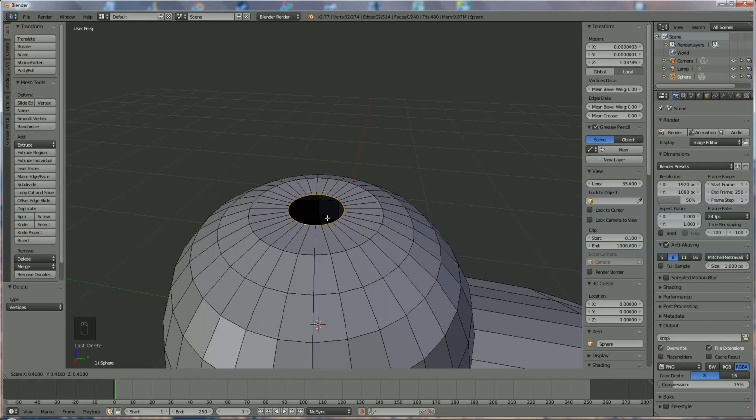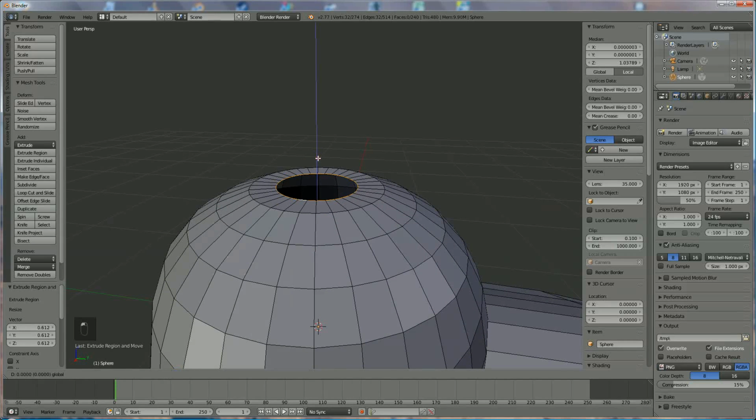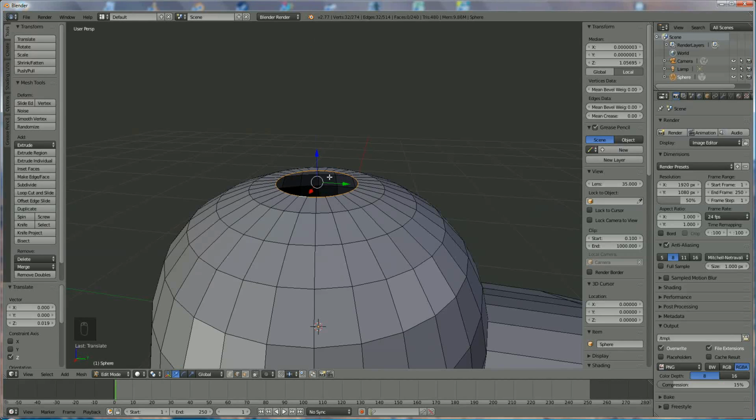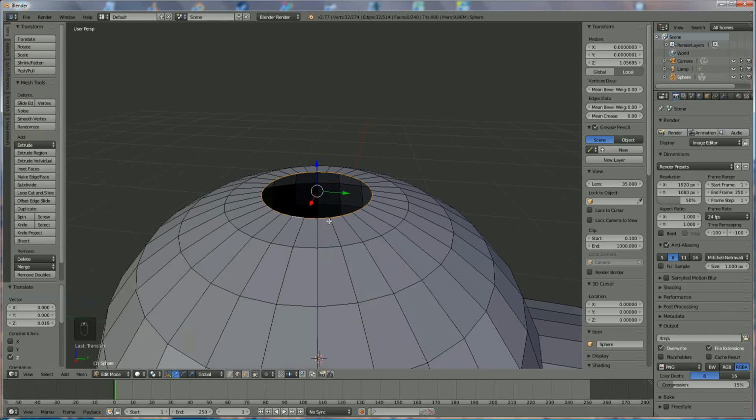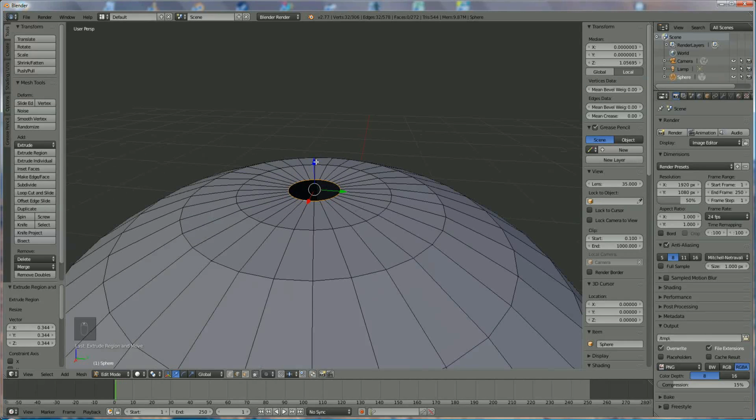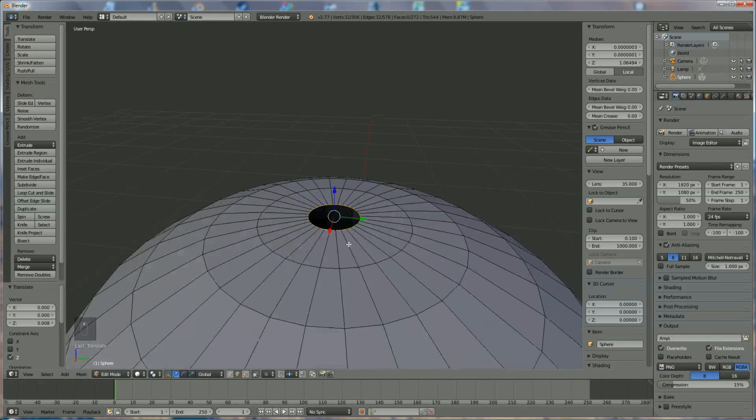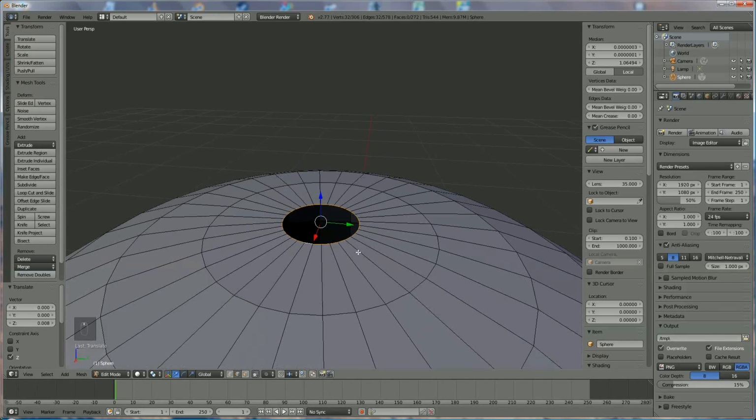We're going to do that for, let's say, somewhere over here. Move it a little bit up so that it follows nicely that round shape. And now we're going to make a little knot. So to do that, we press ES again until we get the diameter of the knot, like this. Move it a little up, okay. And now we're going to form it. To do that, we press E, and now it's in Z direction. This is Z, not too much, something like this.